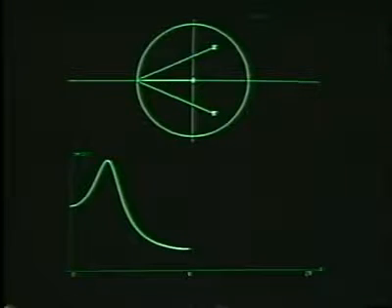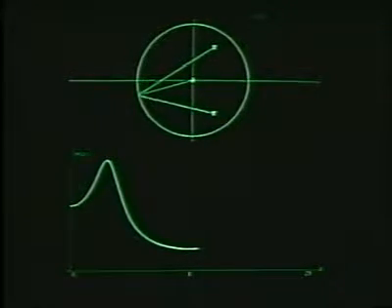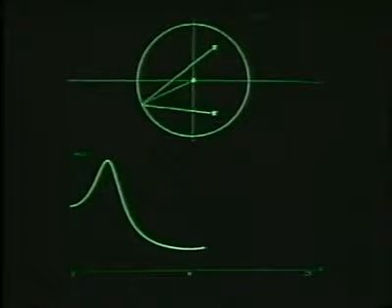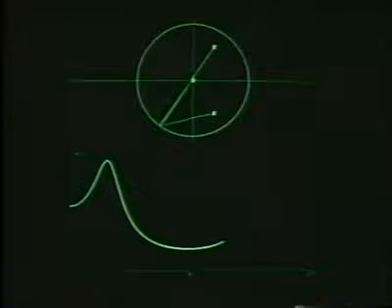Now we want to continue sweeping from omega equal to pi around to 2 pi. And because of the symmetry in the Fourier transform, what we will see in the magnitude is identical to what we would see if we swept from omega equal to pi back clockwise to omega equals 0. In particular now, as we're increasing frequency, notice that the length of the pole vector associated with the lower half-plane pole is decreasing.